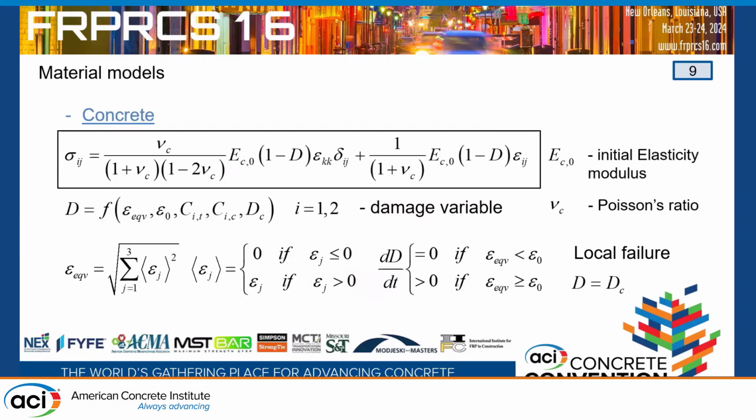So for the material model for concrete, instead of using fracture mechanics, we are using a smeared crack model, rooted in continuum damage mechanics. In the stress-strain constitutive relationship for concrete, we are introducing a damage variable. So basically here we have elasticity coupled with damage. The simplest case is to use an isotropic damage variable. For engineering applications, this yields good results comparing experimental data and numerical data.